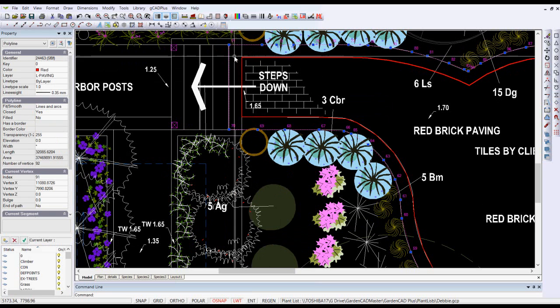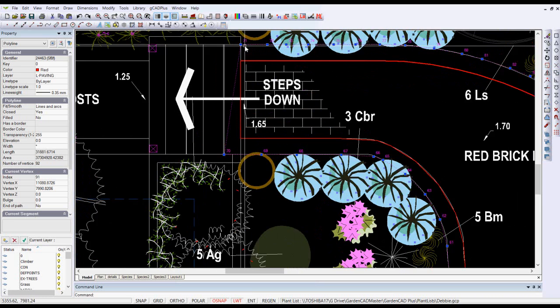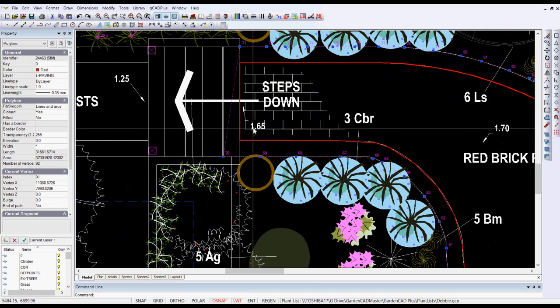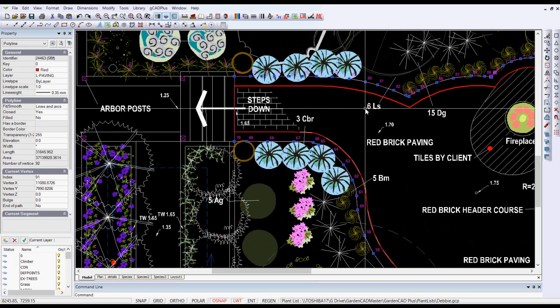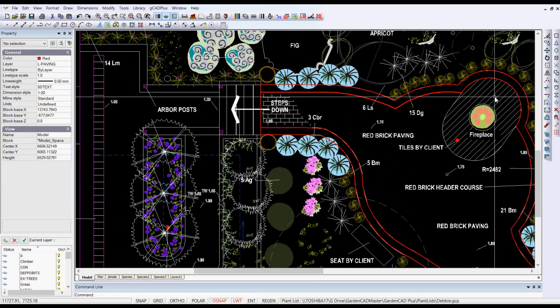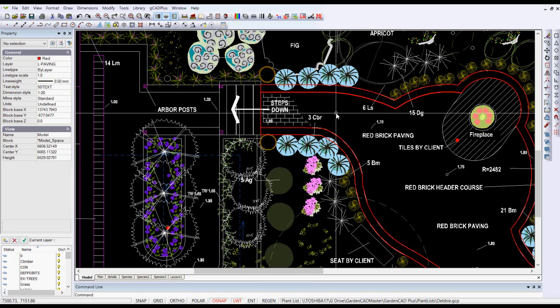let's pick it again, and I'll click there. Now you can see I can move to where I want to be, and I can take a single step offset OSnap, just one OSnap. I'll pick intersection because I want to move that vertex to the intersection of those lines. Similarly, vertex number 70 I want to move, so I click it to make it hot, and then pick intersection again and pick that one. So we now have, let's hit escape, we now have a polyline around the header area, which will work nicely in this instance. So learning to edit polylines is important.